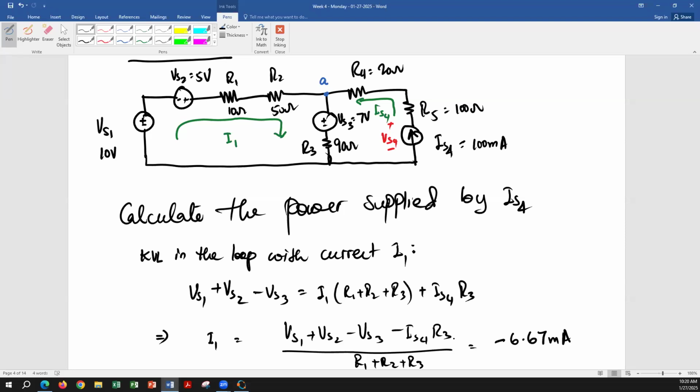All right, what is missing in this equation? So far, this equation is correct. One part is missing. What is missing? Mike, what do you think? I1 R3 plus I1 R3. Yeah, because in R3, two currents are going, I1 and IS.